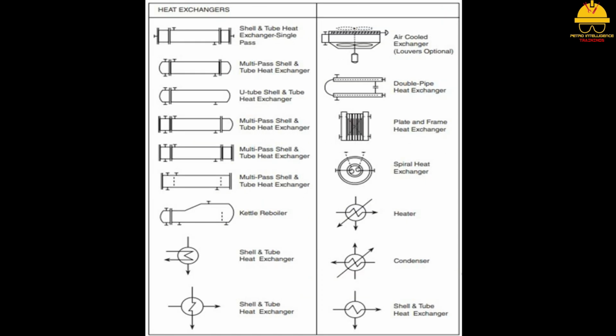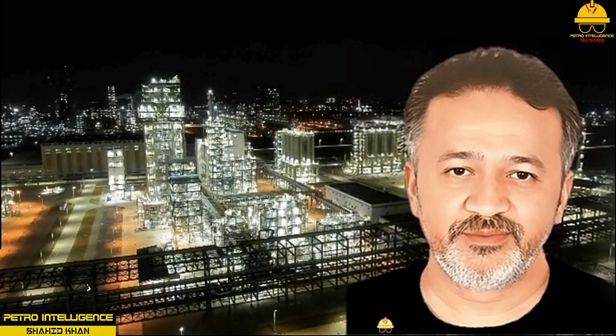Heat exchangers and cooling towers are 2 types of industrial equipment that share a unique relationship. A heat exchanger is a device used to transfer heat energy between 2 process flows. The cooling tower performs a similar function. However, cooling towers and heat exchangers use different scientific principles to operate. Heat exchangers transfer heat energy through conductive and convective heat transfer, while cooling towers transfer heat energy to the outside air through the principle of evaporation.